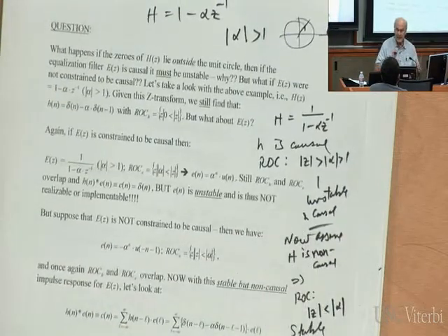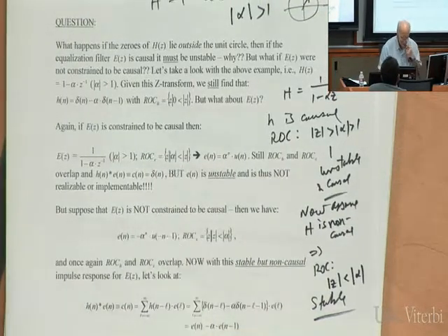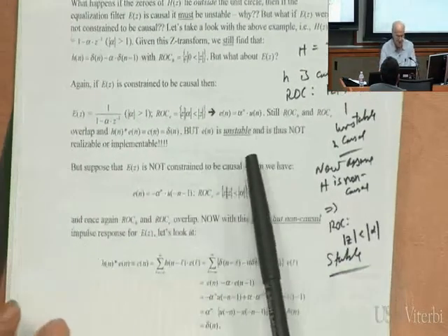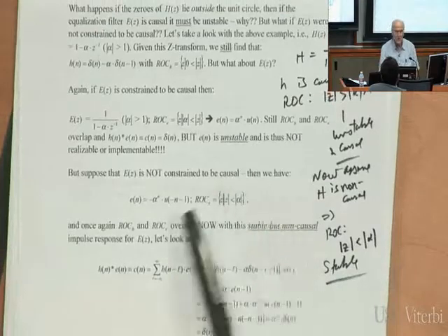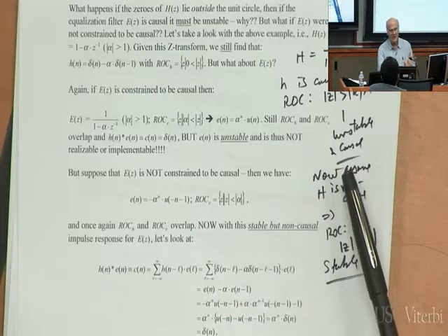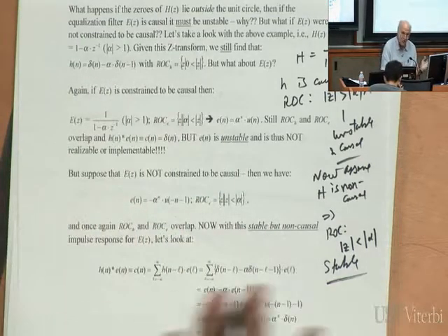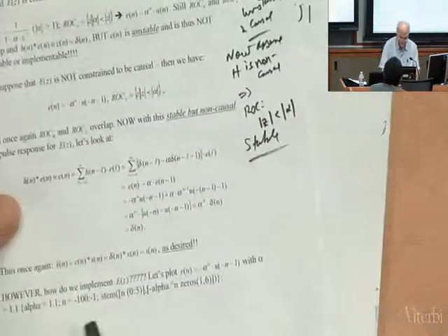So that is why these zero locations, which weren't important before, have now become important. Now the zeros of this filter, when you're talking about equalization, become very important. So what I did in this example, since I have very few minutes, I'll speed ahead to show you what I did. I said, well, look, stable's important. I'm going to give up causality for the time being. I'll make this filter non-causal, but it will be stable. Let's see what I get. I worked all these notes out, plus all the Matlab code that I used to generate plots is in here. See this plot? There's the Matlab code.